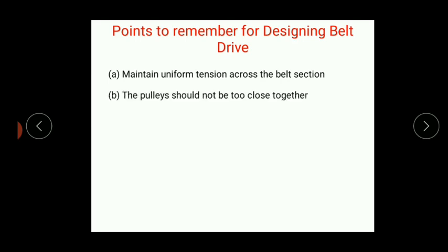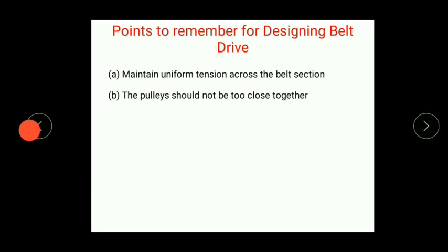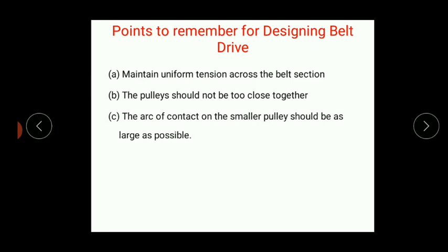The pulleys should not be too close together. Remember, this is a very important factor, because if pulleys are too close, means the power transmission is at a closer range, then instead of belt drive we could have used gear drive. As we had discussed earlier, the power transmission with the help of belt drive is mainly used for longer distance power transmission. Then the arc of contact on the smaller pulley should be as large as possible, because